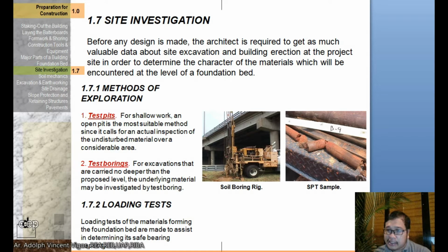There are some soils that can handle multi-stories, and there are some soils that can only handle a single story. It would really affect the design because it would also affect the budget. If you plan to build a high-rise building on a soil that is not stable, you're going to have to spend a lot on the foundation. So that's why it really affects the design.